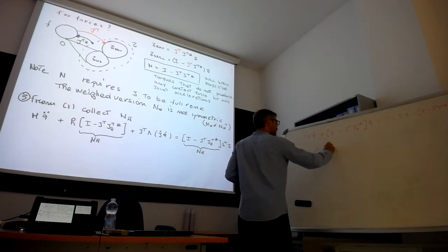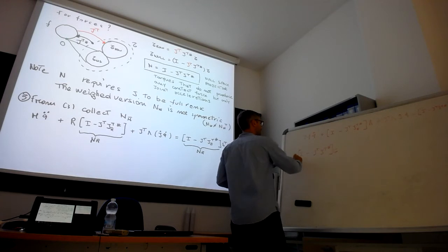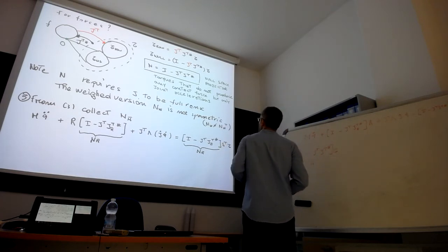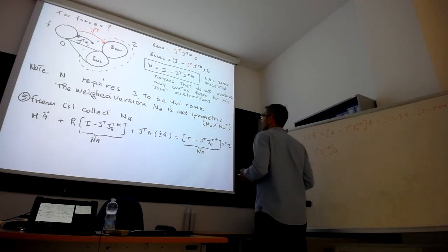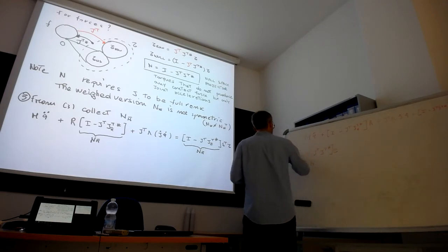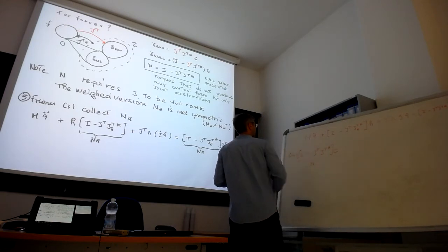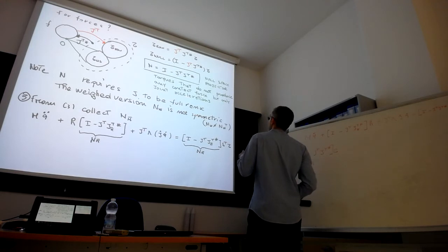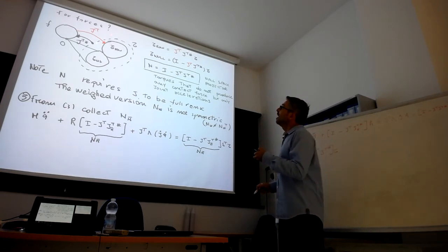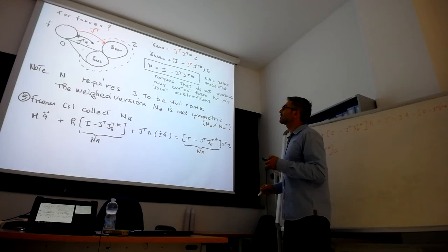So this is, in essence, a null space projector of the J transpose matrix. Sorry, the J transpose pseudo-inverse matrix. And this represents the torques, tau and S, that do not produce any contact force, but only joint accelerations. So they can move the joint internally, but they don't produce any force of the contact.